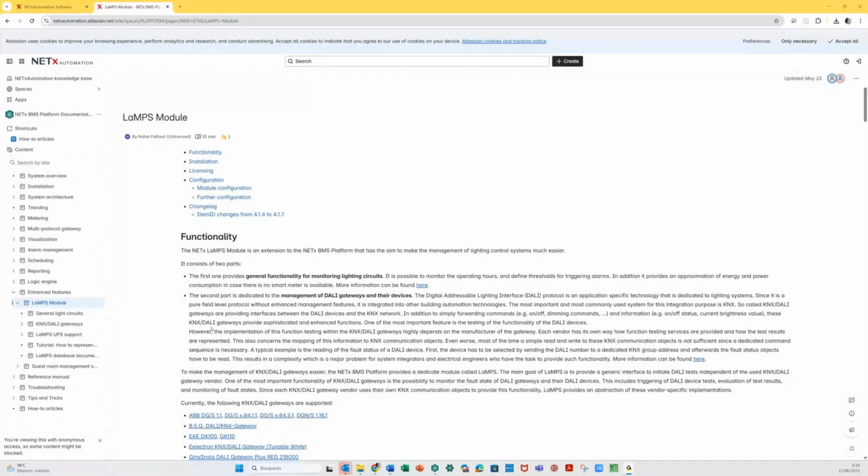So with a very simple configuration, maybe 2, 3, 5 data points, generic for the gateway, not for the lamps, very small amount of data points, we can do this polling, we can do this checking of the gateway, and we can get all this information from up to 64 ballasts, or maybe more, because there are gateways with more than one channel.